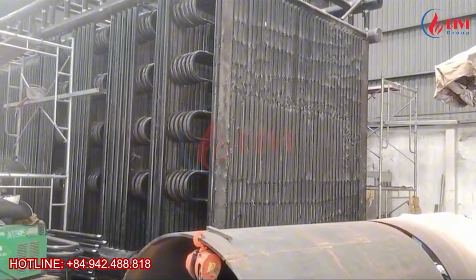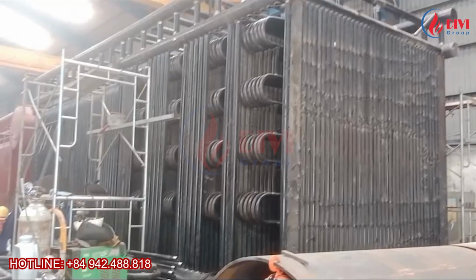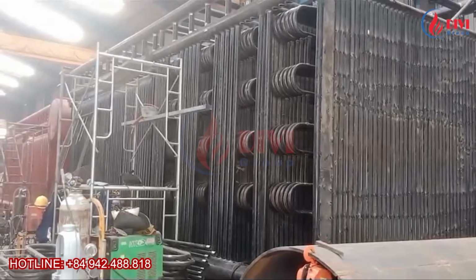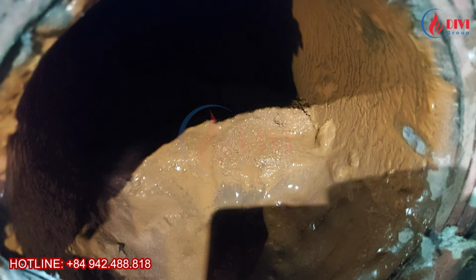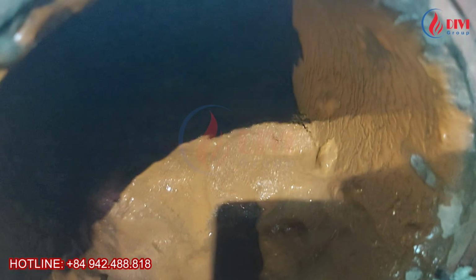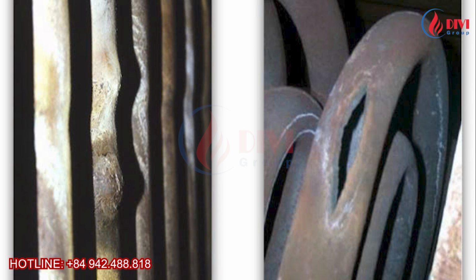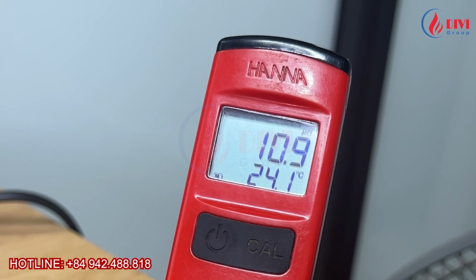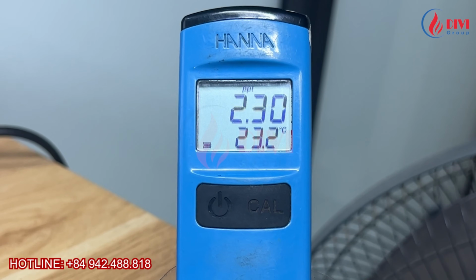However, because this design contains less water and often uses inclined tubes or closely arranged convection tube banks, it is more sensitive to poor water treatment. If water quality is not properly controlled, scale can form more easily inside the convection tubes. When scale builds up inside the water tubes, heat transfer from the flue gas to the water becomes less efficient. This can lead to localized overheating, which may eventually cause tube swelling, cracking, or tube leaks. For this reason, single-drum water tube boilers require stricter water treatment, proper blowdown practices, and closer water quality control.